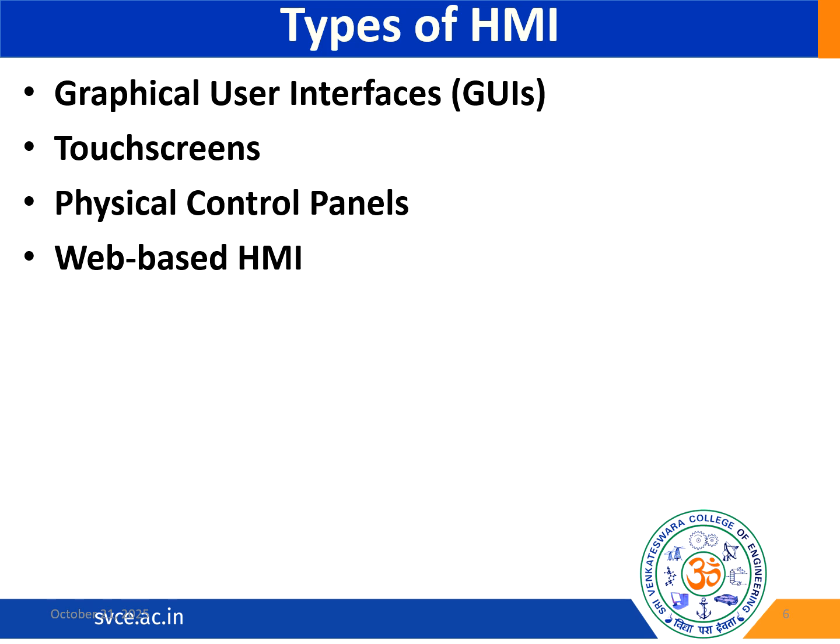When you consider physical control panels, these are physical HMIs that use buttons, switches and displays to present process data, and they allow the operator to input commands. They are often used in industrial settings where GUIs or a touch screen may not be practical, such as environments with high levels of vibration or dust. Next we'll be looking at some physical human interfaces.